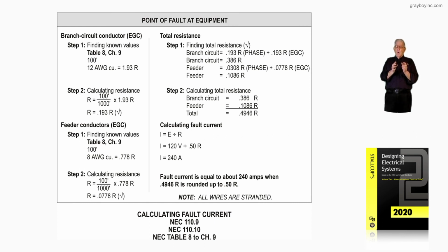But you must be qualified to set them and put them in their settings so that they are accurate and they sense instantaneous. And then when you set them in a certain setting, the instantaneous is gone. They clear quick and lower the energy because it regulates the amount of time the current can feed the arc in the location where you're working. So you read all that in Chapter 9 of Volume 1 of Stallcup's Electrical Design book, or any other book that you choose that would give you this information.